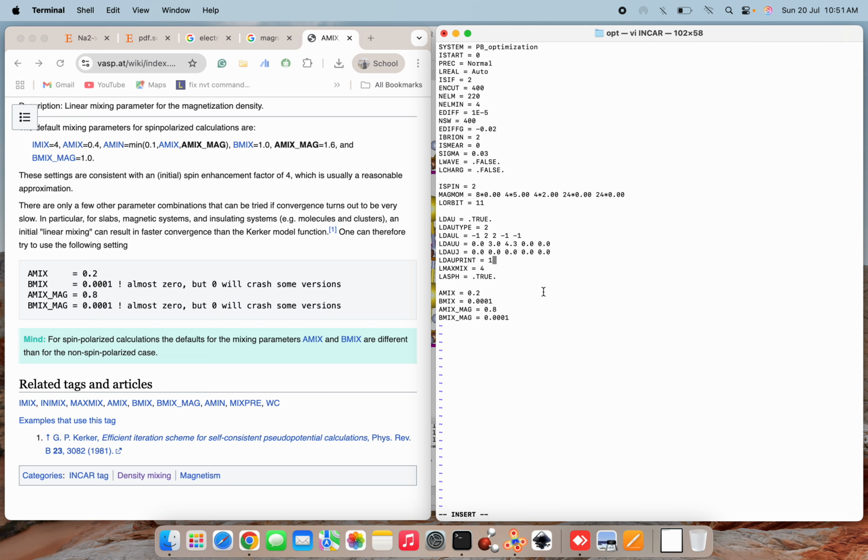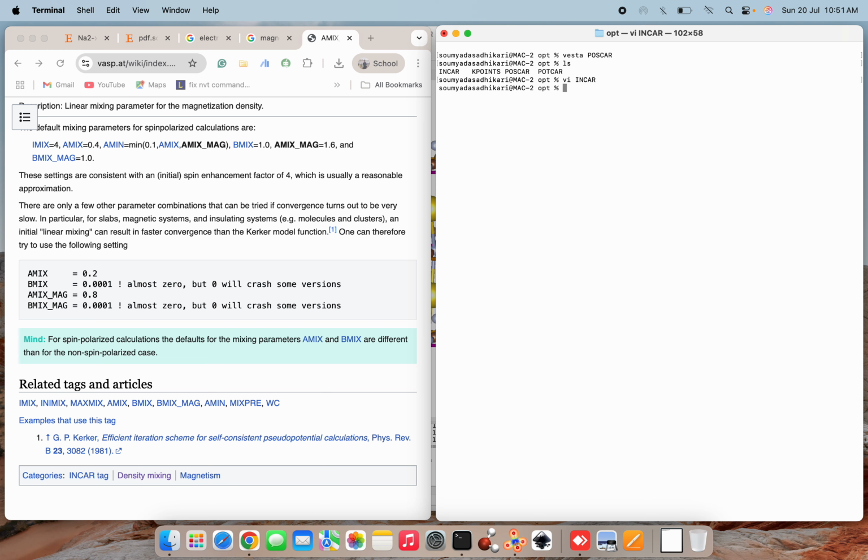And okay, now with all these parameter settings, we have set our INCAR file, and in a similar way you can also set your k-points. Here I have set the k-points like Gamma points 4 4 4, as this is a cubic cell, so along all 3 directions we have the same number of Gamma points. Next is the POTCAR, where we have sodium, manganese, ferrum, nitrogen and carbon.